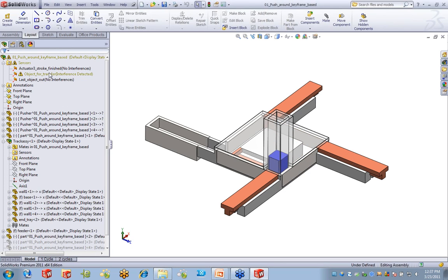And it lets you know when the block has made it all the way around so that actuator 3 can be completed. And then it also has one in here to tell us whether all the blocks are out of the tube. These are all done by adding a sensor between multiple components, and we're going to actually add some for the event-based, but I wanted to show you a little bit of that.